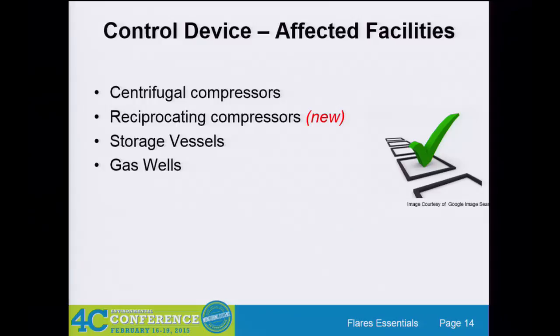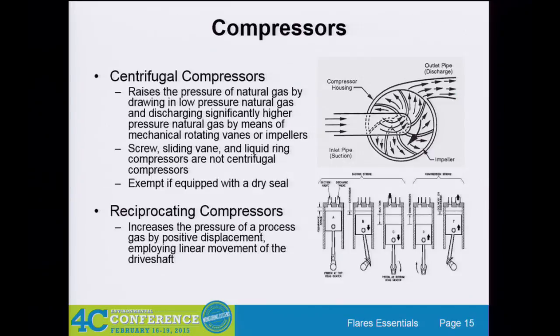It was going to be just to talk about control device requirements for centrifugal compressors, but EPA just added reciprocating compressors if you use a combustion or control device to control emissions from reciprocating compressor rod packing boxes. And then yesterday I was reminded, and we'll get into this, it's centrifugal compressors with wet seals. If you are a mechanical engineer or have a lot of mechanical background, there are centrifugal compressors out there with dry seals that don't use any fluid to maintain the seals. Those are not affected by the rules. So let's get into that, and then we'll take a break.